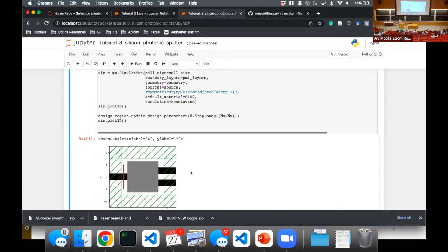That gray represents what we call an artificial interpolation between our two materials that we're trying to design between, silicon and silicon dioxide. Okay, the refractive index is literally a linear interpolation of those two refractive indices that we prescribed earlier. But what's cool is I can arbitrarily choose any of those pixels and twiddle it as I wish. So for example, if I do something like this, rand.